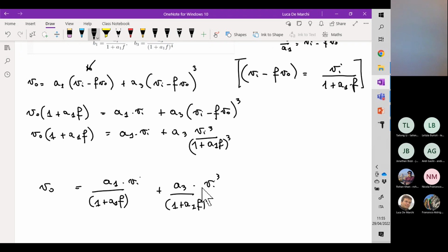Okay, we must be much more careful about the frequency behavior of our circuit, because after the application of the feedback loop, the risk is having poles with positive real parts. Okay, and having such poles with positive real part means instability.